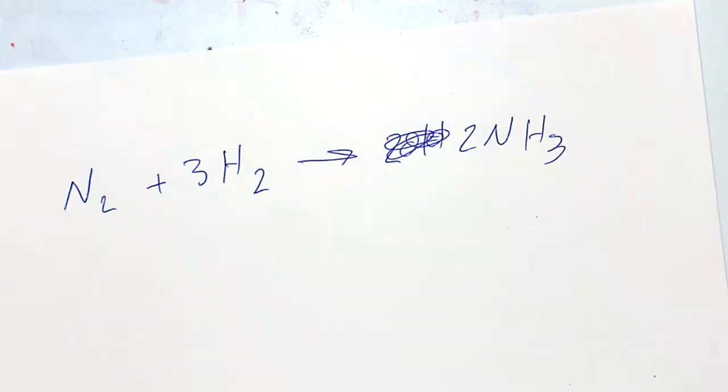That's why, based on experiments and reaction rates and conversion rates, all of them are experimental. You can calculate what is the most efficient route to ensure your reaction is profitable based on the size of the reactor. So you have to take all of this into consideration when you're designing a reactor. But it's quite well proven, it's all experimental. So you do 10, 15, 20 years of R&D, and from there everyone else can copy your reactor within 6 months. So if you're wondering why drugs are so expensive.